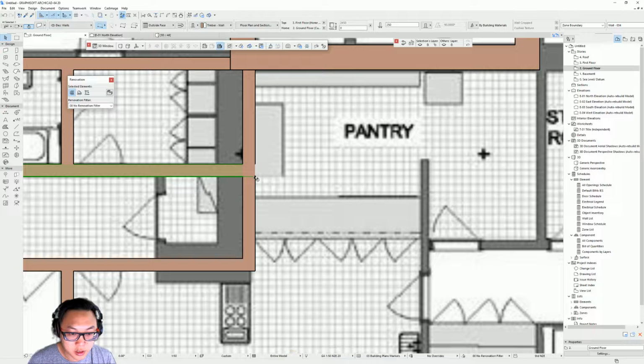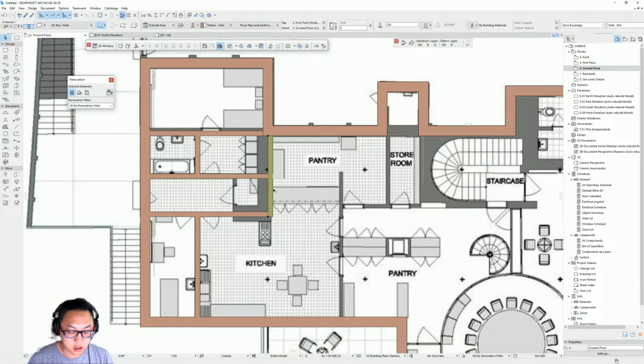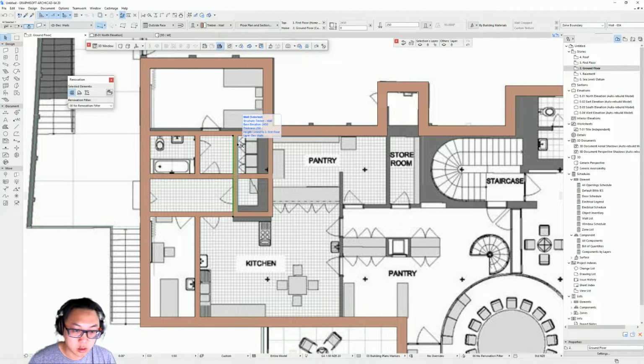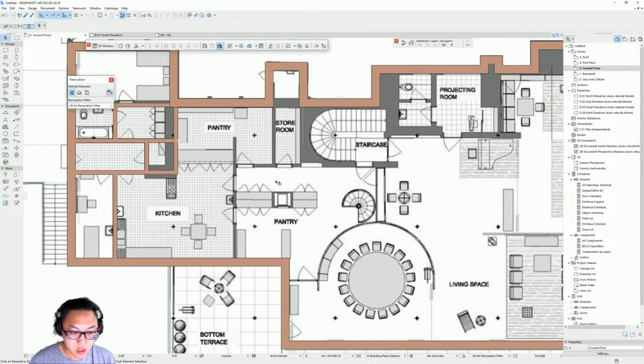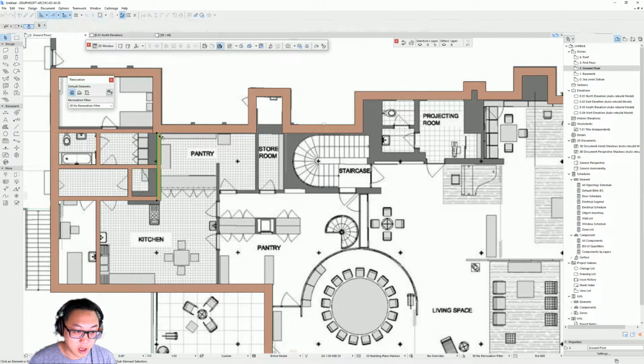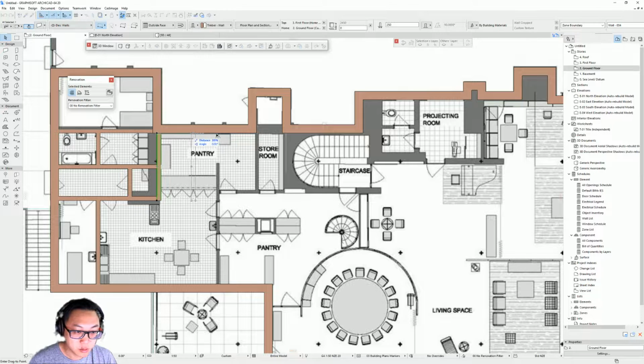And I'm just gonna move that wall here, so I make a copy. Control D, press Control, make a copy, and type in the distance. Go over the wall, select the wall, press Control to get the scissors, click, and let's do the other walls. So that's another technique. Let's say you click the wall, you press Ctrl D because you want to move it, I'll make a copy. If you press Ctrl, you're gonna have one copy. If you press Ctrl Alt, you get plus plus plus, and that allows you to make multiple copies of that same wall.